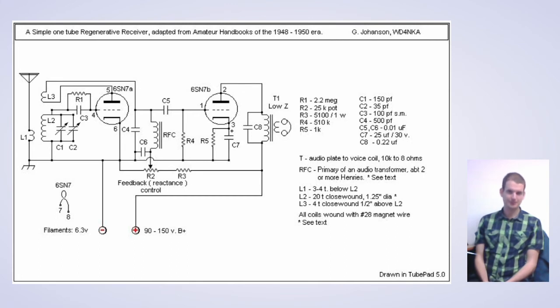Let's take a look at a simple two-tube radio. The signal from the antenna enters the resonance circuit which consists of a coil and a capacitor. This resonance circuit is used as a filter. We can use this to choose the frequency which we want to hear. The signal then enters the first vacuum tube because it's connected to its grid. This grid regulates the current in the